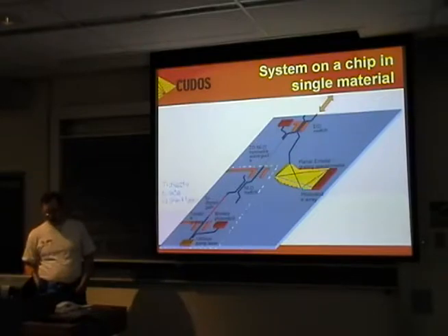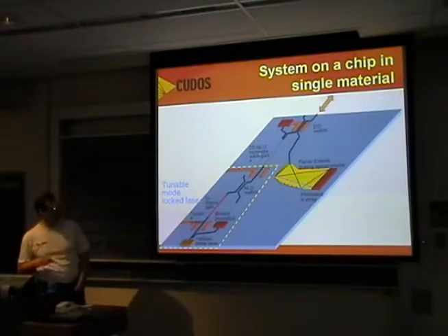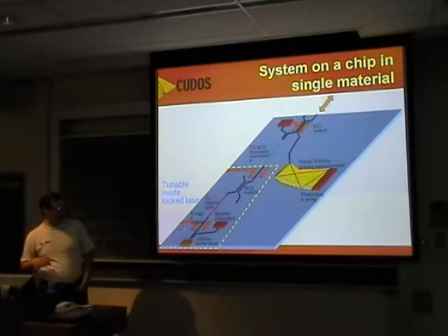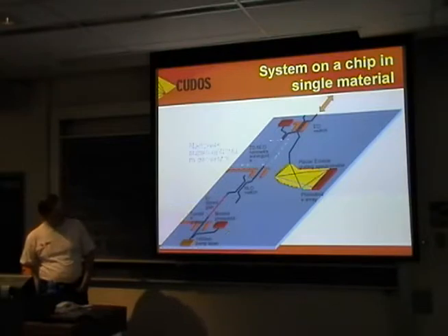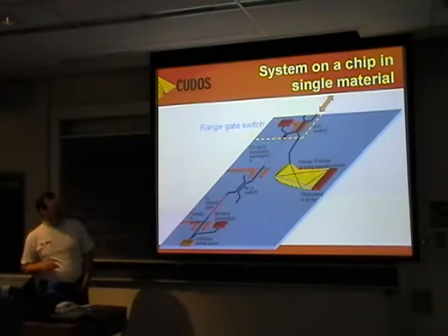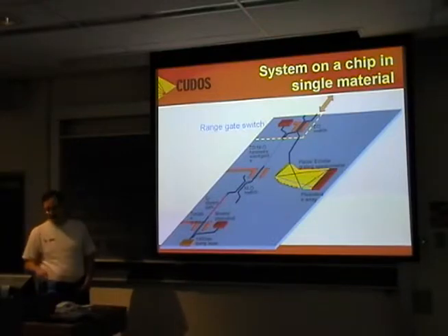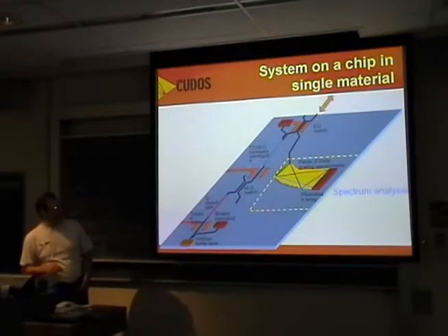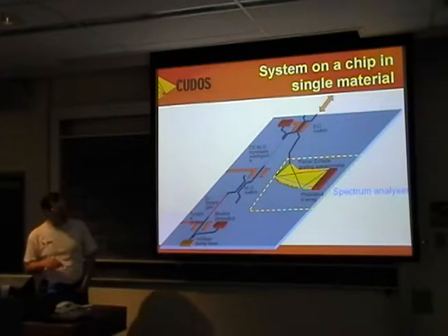So what we've got in this schematic here is a tunable mode-locked laser, based on rare earth-doped waveguide gratings and a nonlinear switch. Up here we then go down into a nanowire device that will generate supercontinuum. And up here an electro-optic switch so that we can switch the pulse out and then gate by distance what comes back and go into a spectrum analyzer on chip here.